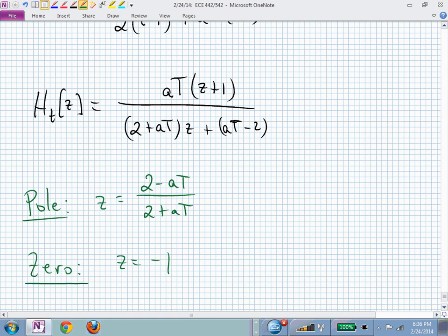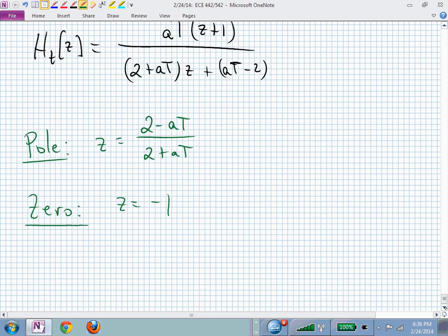The last one was at 0. We can kind of argue that those 2 points in the z-plane are sort of like infinity, because the imaginary axis maps to the unit circle, and we just go from 1 to minus 1. Minus 1 sort of looks like infinity. If we were looking at a pole on the real axis in the z-plane, it's really slow at z equal to 1, and it gets really, really fast as we get closer to the origin. So z equals 0 could also be thought of sort of like a point at infinity in the z-plane. But here, this discrete equivalent is saying our 0 is at minus 1. What about our DC gain?